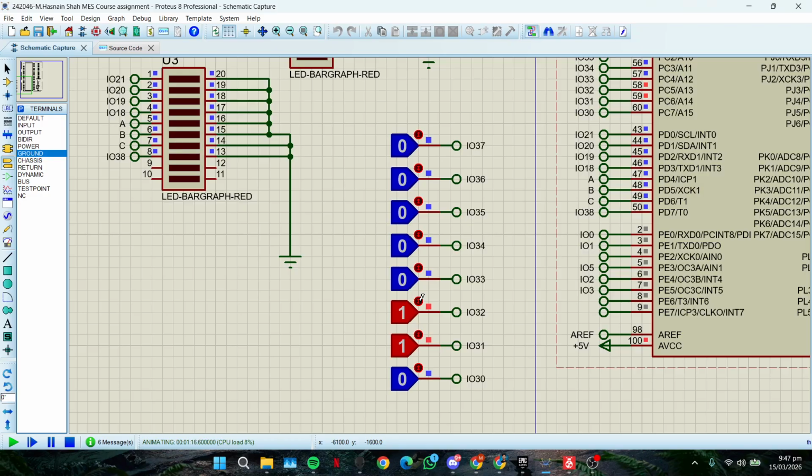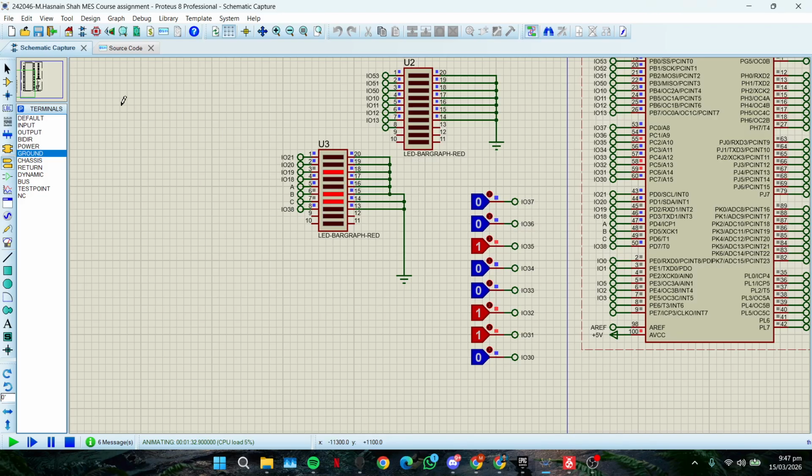Now this gives us 96, still on port B. But the moment I click on PC2, here is PC2, 0, 1, 2. This is PC2. Let's toggle this. Now we are at a total of 100. Now let's look at the bar graph. The data instantly vanishes from port B and appears on port D. So we are exactly equal to 100, port B is completely off and the data is on port D.